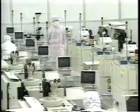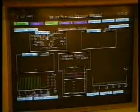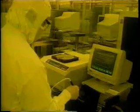One important aspect of understanding the cost of a product is to understand the cost buildup of the product as it flows through our factories. The cost of a product very early is basically just the raw materials and a low amount of labor content of a wafer as it comes into the factory, a wafer that may cost $40 for the raw substrate and is going through 1 or 2 mask steps. Again, the cost we've invested at that point is relatively low. After that wafer has been through the wafer fab process and been through 20 or more mask steps, we have upwards of $500 invested in it.